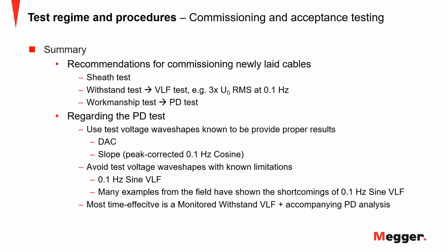Again, just a summary for the commissioning test. Just in short, sheath test, highly recommended, has a lot of value, especially long-term. Withstand test as per the standard. The workmanship test is the PD test, revealing assembly faults.